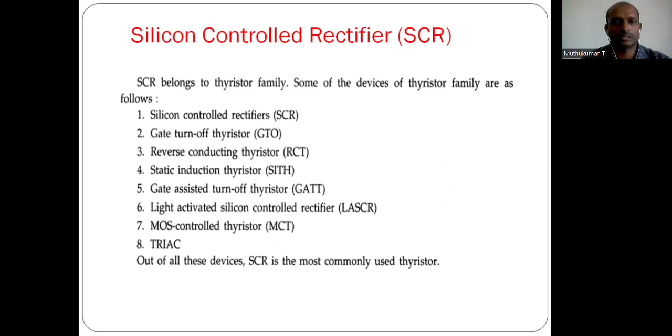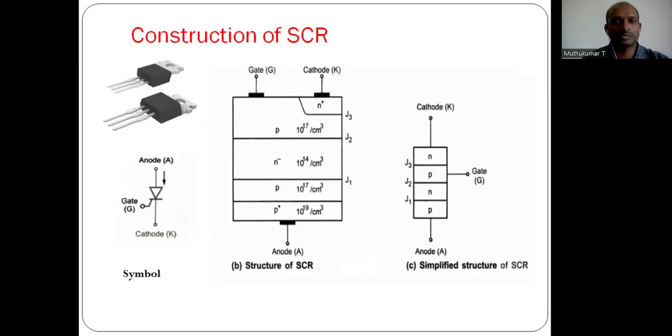In this, I'm going to discuss the silicon controlled rectifier, which is one of the thyristor family. SCR is silicon controlled rectifier, GTO gate turn off thyristor, RCT reverse conducting thyristor, static induction thyristor SITH, gate assisted turn off thyristor, light activated silicon controlled thyristor, MOS controlled thyristor MCT, and triac. Among these combinations, SCR, that is the thyristor, is the most widely used power electronic device.